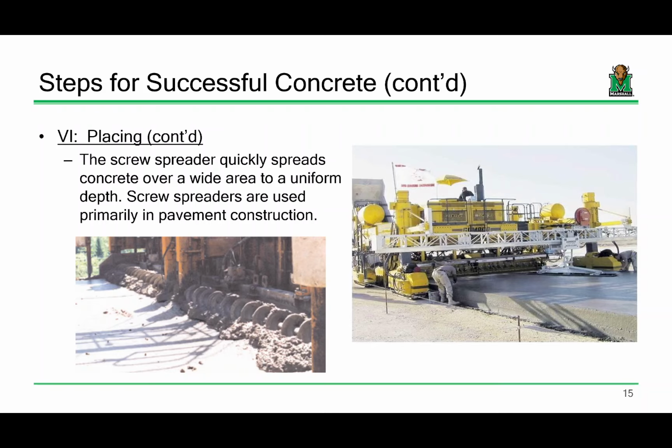Okay. Once the concrete is placed, we also need to level it out. Sometimes, depending upon the placement procedure, or maybe specifically the product that we're placing, we can combine placing and finishing at the same time. So you'll see this in long continuous casts for things like road projects, maybe slip forms on Jersey barriers on DOT projects. Has anybody ever seen those where they're casting the concrete parapet as the road goes and whatnot? So you're essentially depositing the concrete and finishing it at the same time.